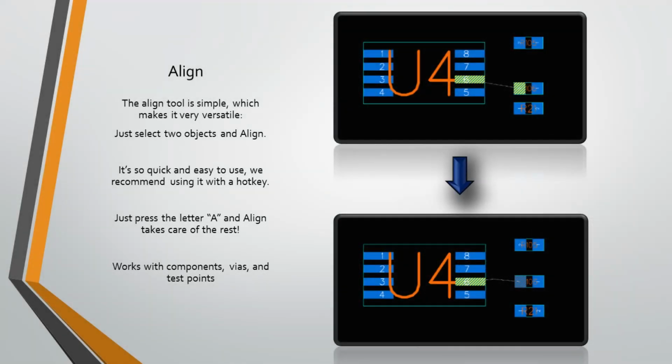The Align tool was born from the frustration of placement grids and component pin grids not matching up, and the traces going from one part to another having a lot of unwanted jogs and corners in them. Long ago, all components were made on 25, 50, or 100 mil grids, so it worked well to place all of them on a 25 mil grid and put all of the vias on a 25 mil grid as well. This made for a clean routing setup that allowed long straight traces going all the way across the board with nothing in the way. Now, most components are built on metric grids with often random pin spacing that does not match up at all with a 25 mil placement grid.